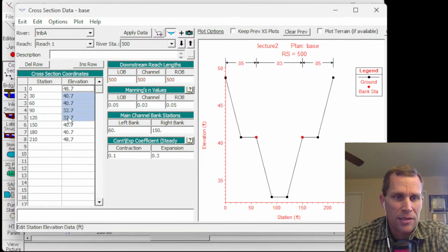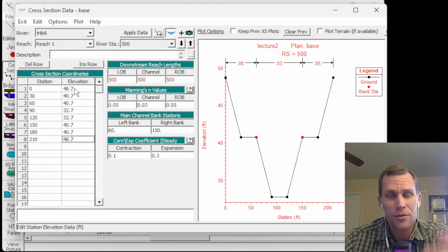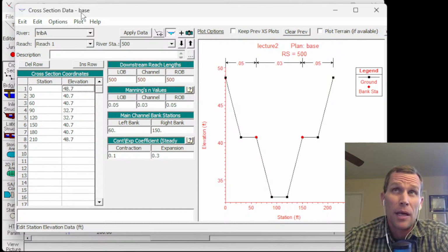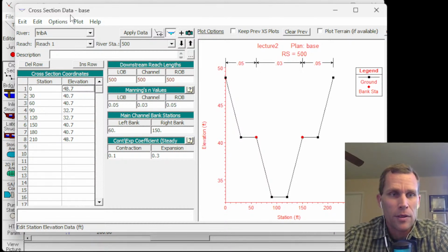And then the one other thing I need to do is update the elevation. So I need to increase the elevation a little bit. So of course the water flows downstream towards that junction. I'm going to add 0.1 foot. I'm sorry, I'm going to add 1 foot, and then that would be a 0.2% slope because it's a 1 foot change over a 500-foot length.